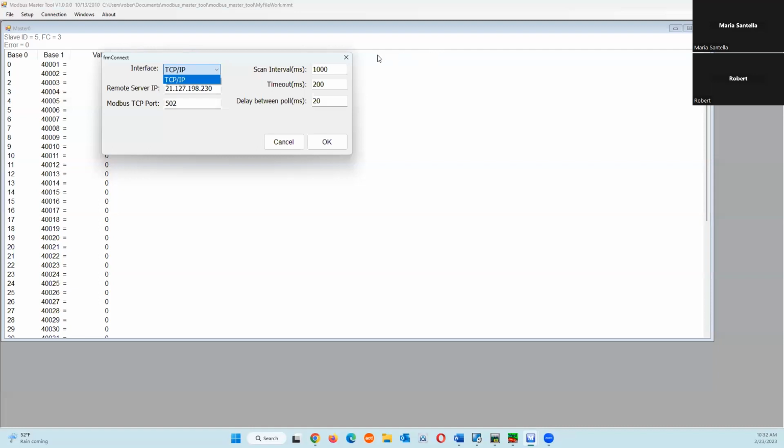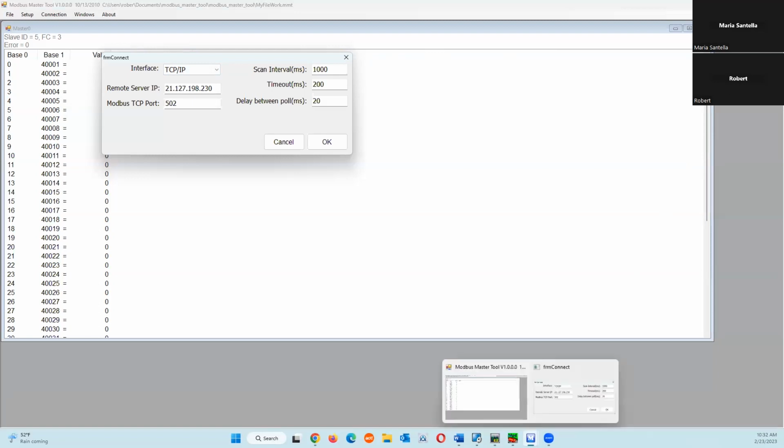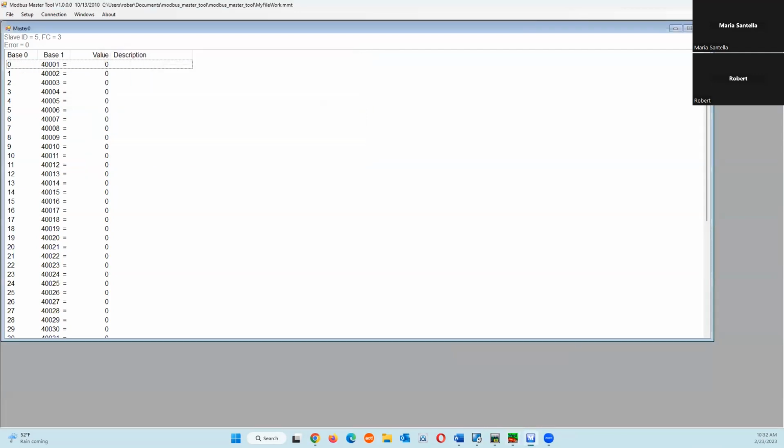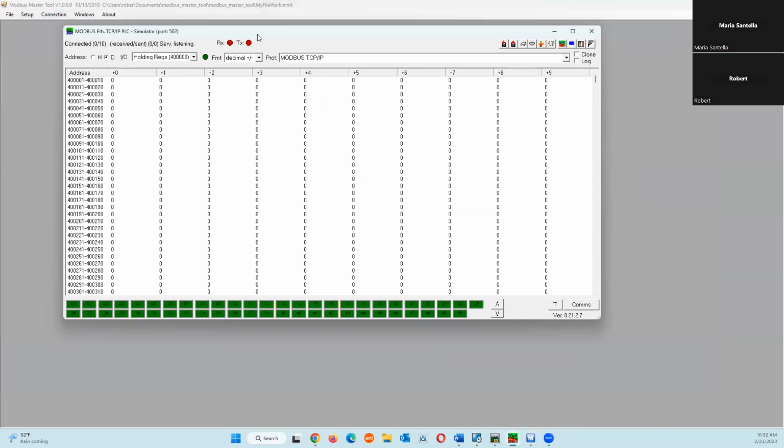The opposite condition, where you have a Modbus Master, like one of our WinPAC or XPAC controllers, you can use a software package which I was shown by a customer actually. It's called ModRSSim. Let me just slide this over for you. With this one, you can use your PC as a Modbus RTU or TCP slave device. So if you wanted to test communication from your Modbus Master, you can set the software up to mimic the Modbus RTU or Modbus TCP slave device.